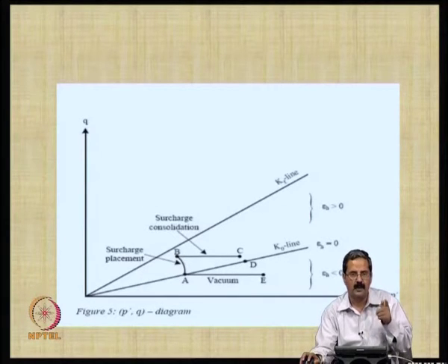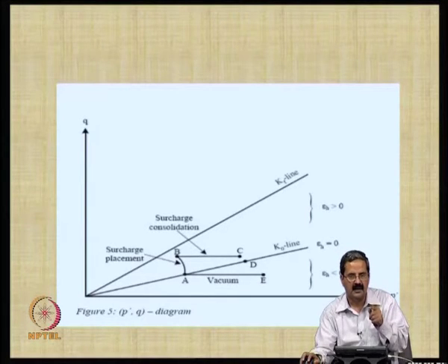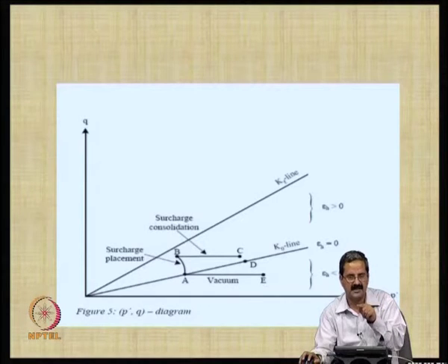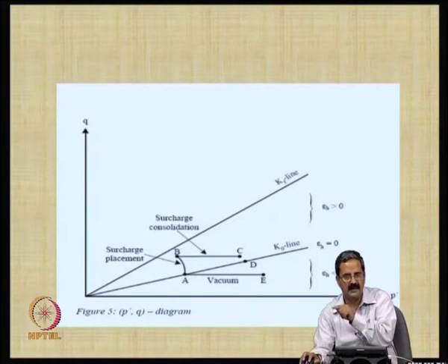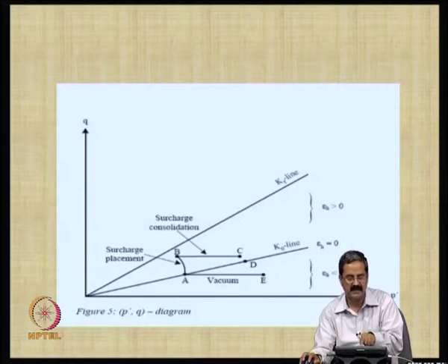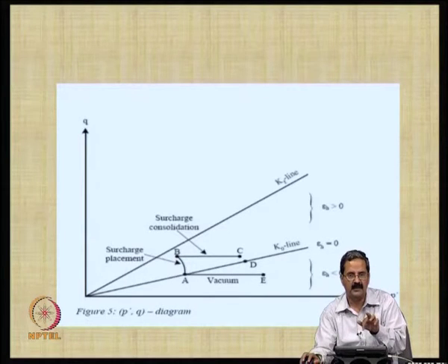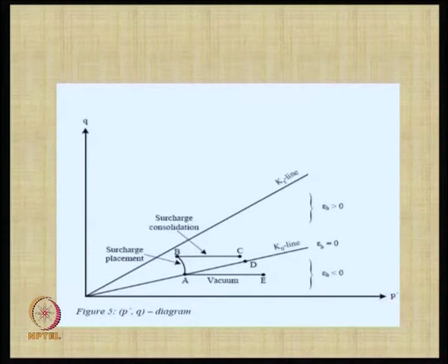So, for example, pore pressure is generated, and you say sigma dash equals total stress minus pore pressure, minus this plus, actually this becomes additional. So, the effective stress will increase because it is the opposite of pore pressure, it is a suction, it creates a suction. So, in the process the effective stress is increased: the effective stress equals total stress minus pore pressure plus suction.